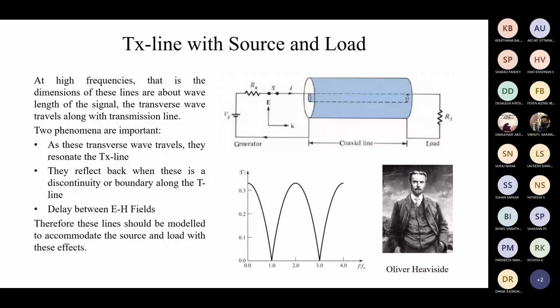So we already discussed why this transmission line theory is required. About 100 years ago, many experts, including Hertz as well as J.C. Bose, described that when a wave is traveling in a wire, it gives completely different resistive behavior. This resistive behavior gives reflections in the backward direction, and that is why maximum power is not going from the transmitter to the receiver. Moreover, there is a delay taking place.